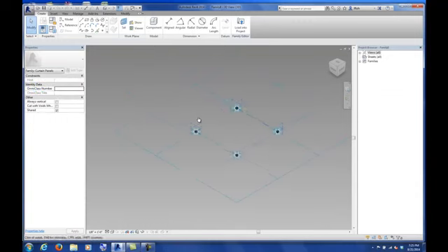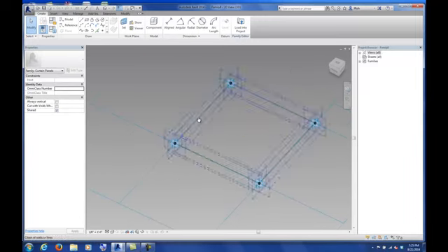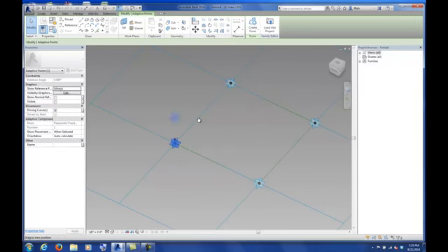So this one kind of makes sense why they call it what it is, that it has an underlying pattern that's associated with it. There's some adaptive points. They're kind of on a grid. We can move these points. I'm going to take this point and just drag it up and down, and it drags off the grid. And this is kind of a practice I like to do, is actually move all of these off the grid.